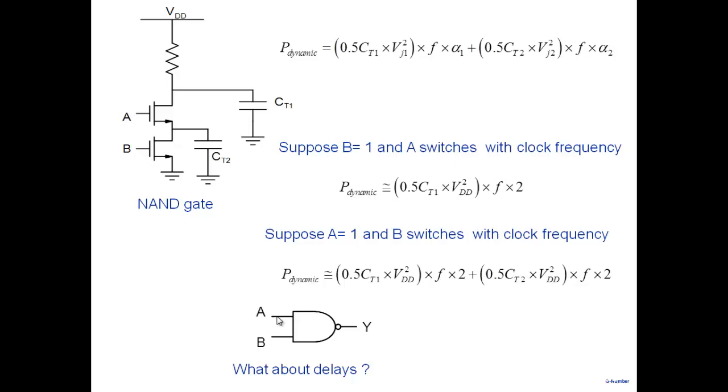In general, you'll find that the inputs to the gates are not equivalent. They are not equivalent. For example, the delay from A to Y and B to Y are in general different. Delays are different because the position of the MOSFET does matter. So think about why the delays would matter. In which case would the delay be higher, from A to Y or from B to Y?